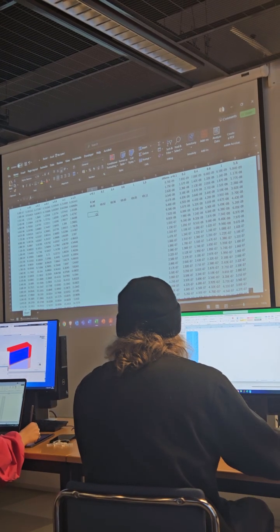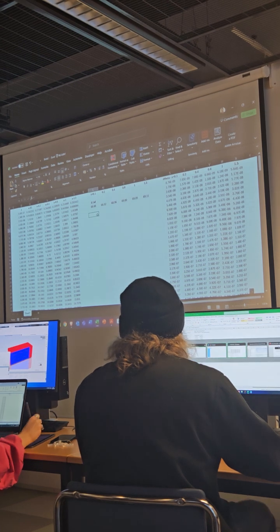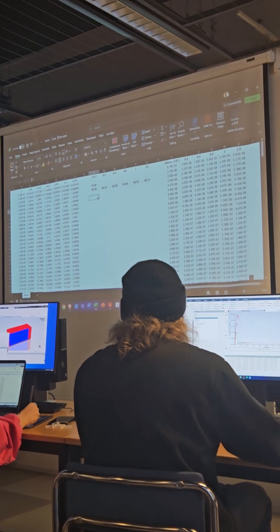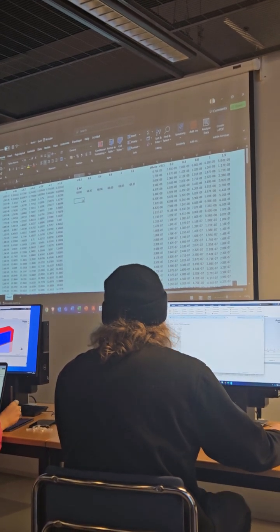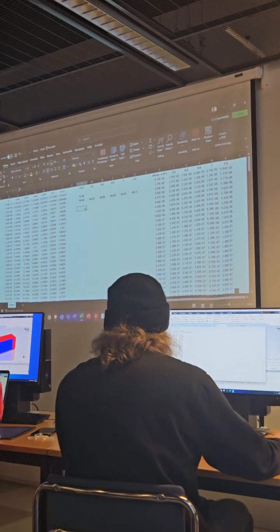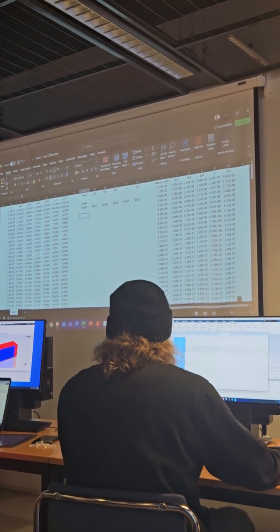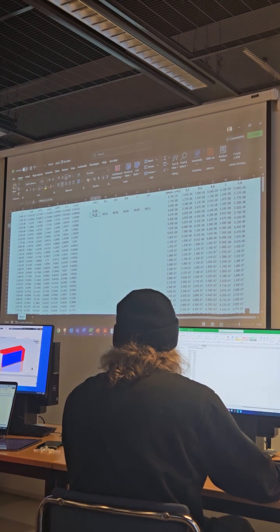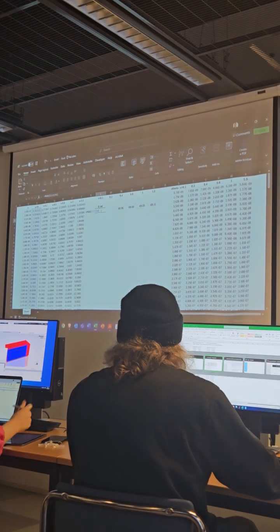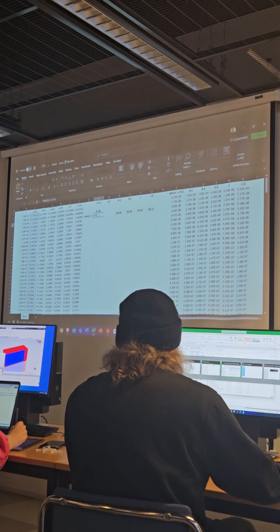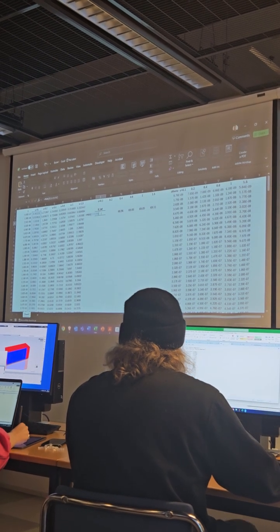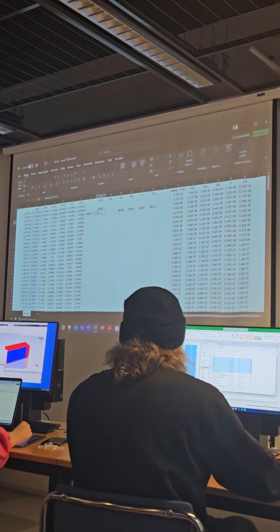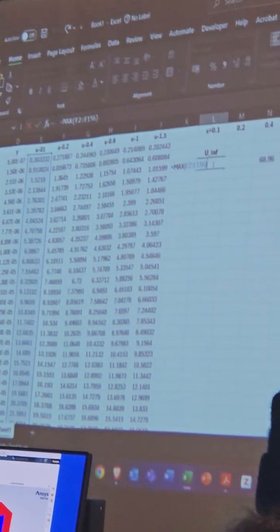So the delta theta values for each section that I'm dividing my line perpendicular to the plate. Sorry, can you just repeat it again? At u infinite, at which position did you select u infinite? Right. U infinite is the maximum value of this column. So for example, u infinite at x equals 0.1 is the maximum value of the velocity distribution at 0.1.